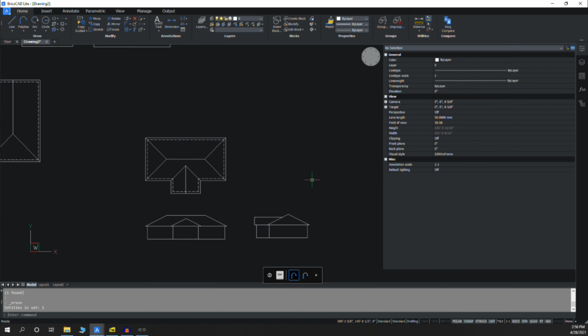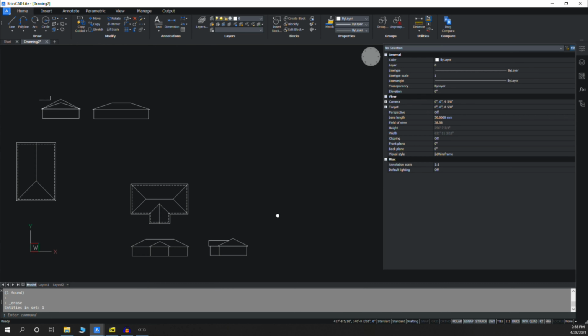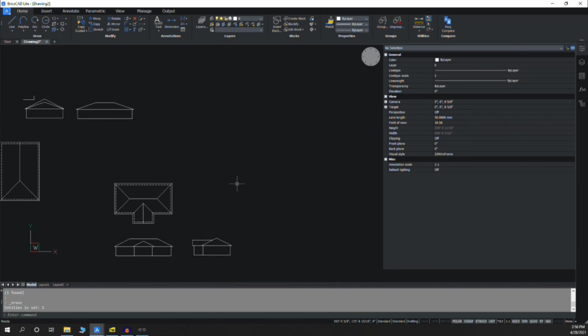So that works for any size building. You just kind of use those measuring sticks, mirror, do that little technique where we're trying to get the 6/12 pitch. You could use any other pitch if you wanted to, a 12/12 even. You just go 12 feet up and 12 feet over. So that will cover probably 90% of roofs.